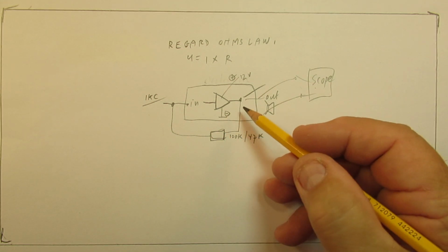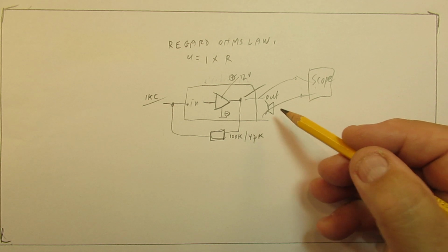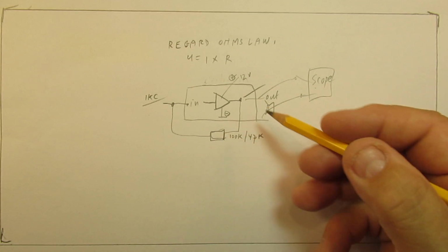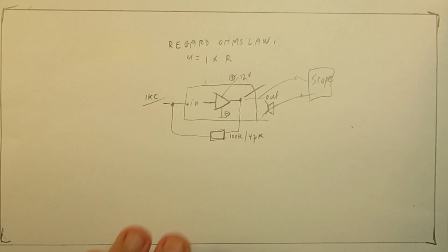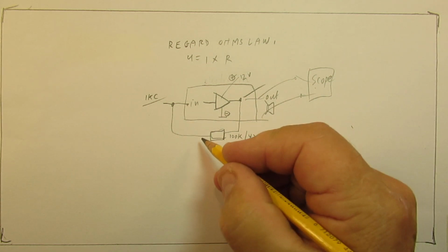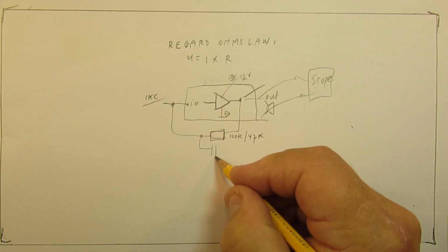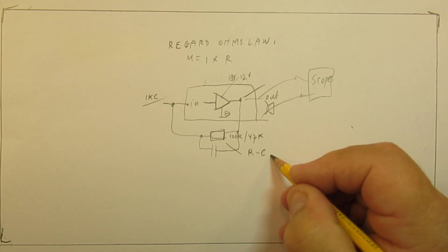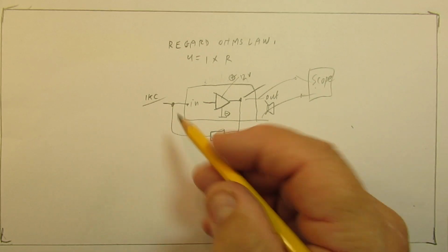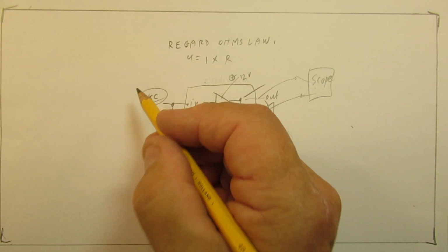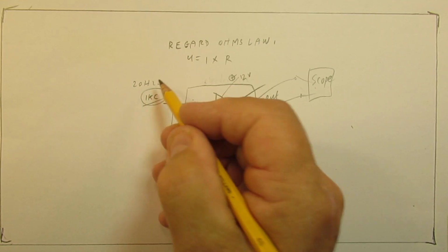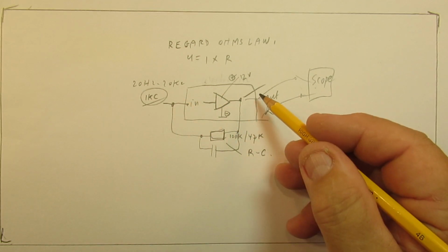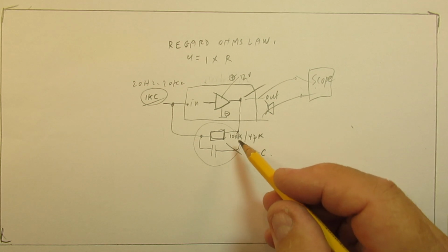That means that you could get a kind of damping. It could change the output level, but more important, for instance, when you use in this case a capacitor, this is a time dependent circuit. It's an RC circuit. That means that when this is not 1 kc but say audio, 20 Hertz to 20 kc, and you send a part of the signal back to the input, this is a frequency dependent unit.